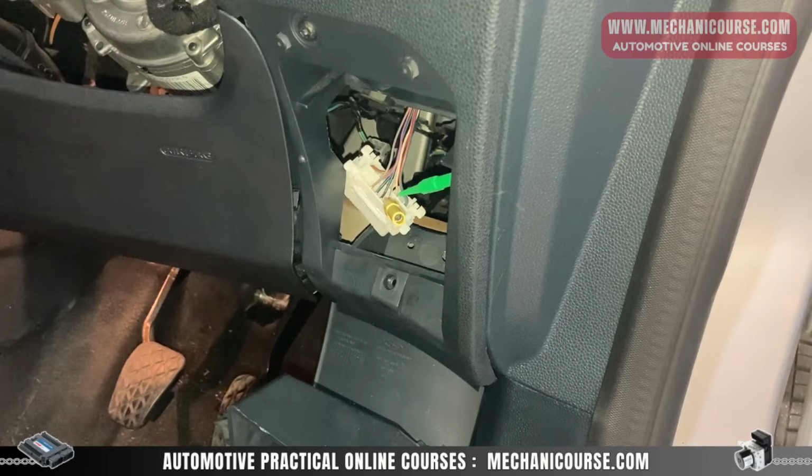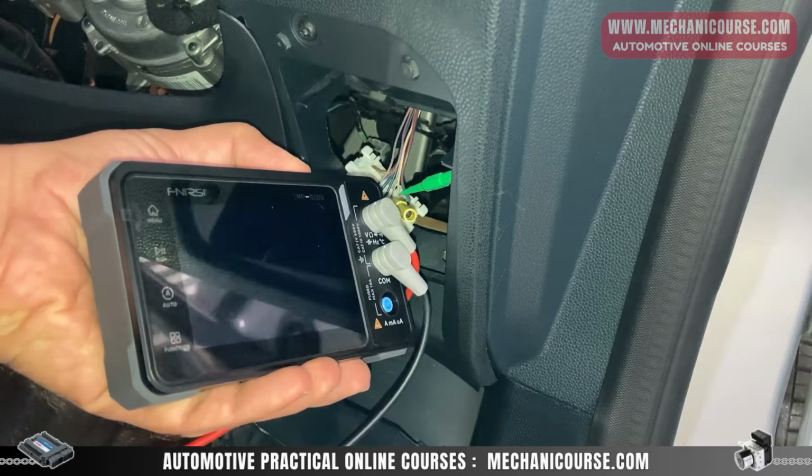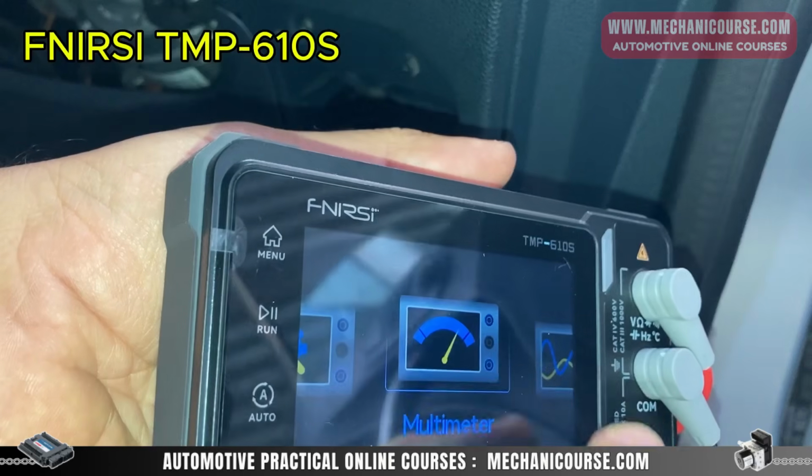We go first for checking the voltage on the CAN bus high and low, and if we cannot find the issue, we're going to read the waveform as well. For performing this diagnostic today, I'm going to use this device from Fnirsi, which is basically a multimeter, oscilloscope,